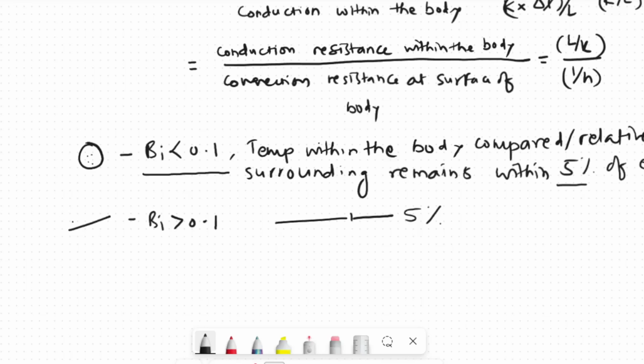So we'll apply the lumped parameter analysis to the copper ball, and for the food material of bigger sizes, we'll be using the unsteady state heat transfer and some of the charts made by Heisler and Gröber.